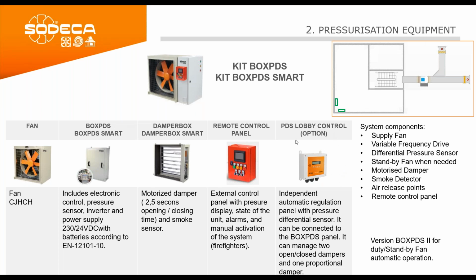As an option, we can connect a number of PDS lobby controls to the Box PDS control panel. This device allows independent automatic regulation, and we use them basically for lobbies. We can install one PDS lobby control at every lobby. If you remember, the first webinar said that when we have to pressurize lobbies, we have two options.